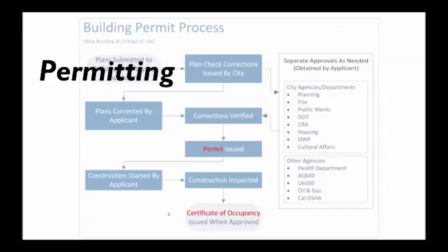builder or the contractor is the one actually submitting the application, because whoever submits the application is going to be the one that calls the city or whoever's checking on the permit periodically to get inspections. So whoever's building it, as they go through the process of building it and documenting its construction, then periodically they're going to have to call for inspections. And each one of those inspections will fulfill a certain requirement of the permit.